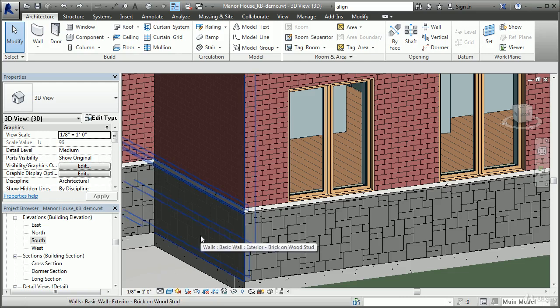Parametric objects are a common feature in many modern software packages, but Revit extends the power of parametrics by allowing you to create intelligent relationships between objects. A floor, for example, can be attached to a set of walls which encompass the floor. When you move a wall to resize the structure, the floor will also automatically resize to follow the new shape of the surrounding walls. Many elements such as walls, floors, roofs, etc.